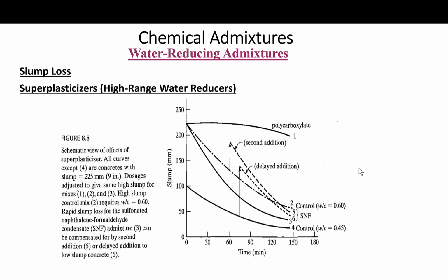What I have to say is, retempering concrete with water to restore workability is an absolutely rejected practice, because it will result in the increase of the water cement ratio. As I said, using additional water reducing agents and an additional dose of admixture during retempering can reduce or eliminate the need for further water. Do not add water. Just make sure the dosages of the admixtures are planned to be added at certain times to maintain the slump for easy placement.